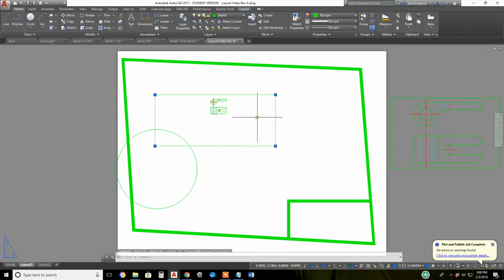Now let's select the viewport. Remember, it's a paper space object. You got to be in paper space. Word paper at the bottom, triangle, all that. Let's move it from the object layer to the viewports layer. Again, it'll never plot. Some people, very rarely, have used the viewport as a border for their drawing. I recommend against it. I've had hard luck making it print out bold on the paper. So put it on a non-plotting layer and build your border separately.